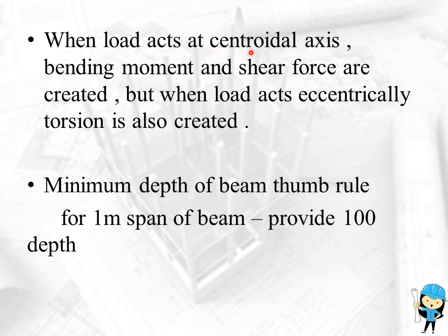When load acts at the centroidal axis, bending moment and shear force are created. But when load acts eccentrically, torsion is also created. Minimum depth of beam thumb rule: for 1 meter span of beam, provide 100 mm depth.